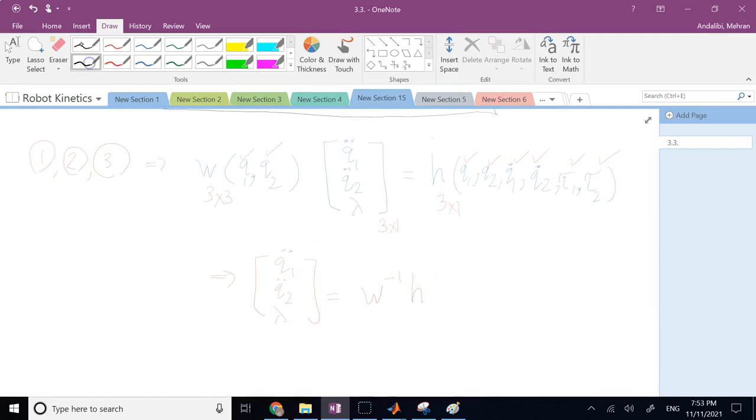And then all you need in that calculation are the first 2 components of the result. Do you care about lambda? You don't. So this is how you go about solving your inverse dynamics problem if there is a Pfaffian constraint involved.